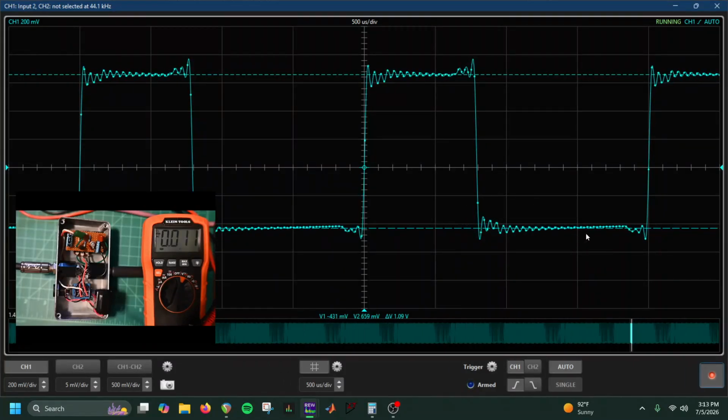And rectification, where we're giving that biased gain on one side versus the other, is going to generate even-ordered harmonics. So if we, again as a thought experiment, scaled everything back to a 1 hertz signal, we would see harmonics at the 2nd, 4th, 6th, and 8th frequencies. So yeah, what else do we have here?